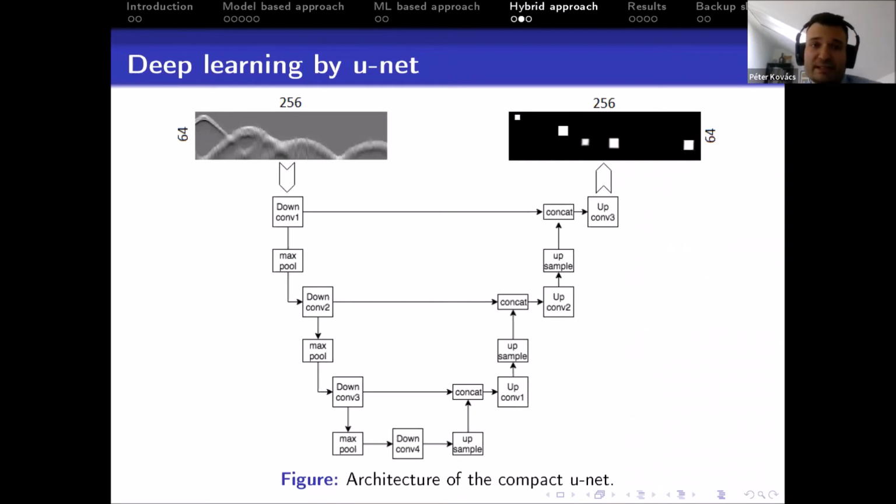We would have the same drawbacks in case of thermography, because in this case, we should make physical phantoms where the defects, positions, and shapes of the defects are predefined. So we could make a lot of training data based on those specimens, and then we can perform the training. But making such a lot of physical phantoms where the defect shapes and positions are known a priori is also costly. So we have a limited amount of data here as well, and this is why we selected the UNet, which can handle this problem.